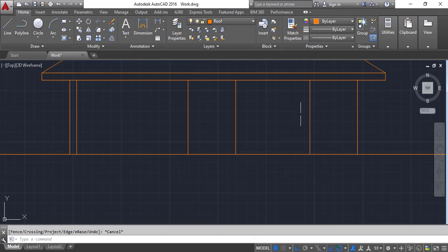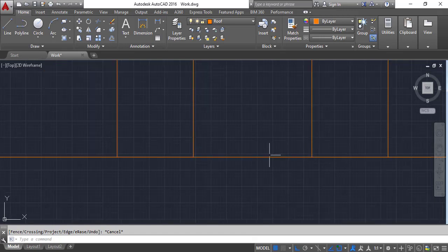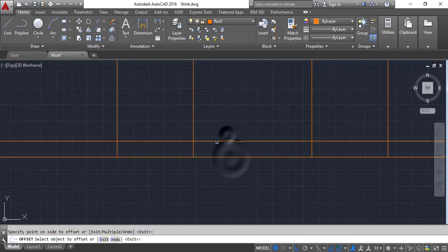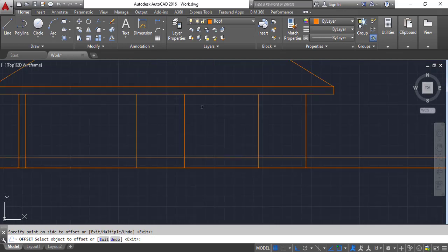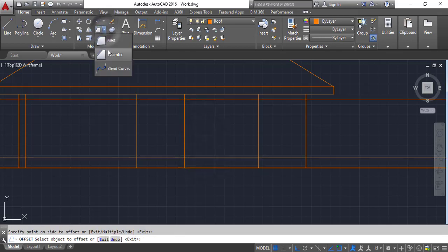And here this is my door, and this is my window. In here I'm going to keep my window height 1 feet. I'm going to leave this wall 12, enter, and here to here I'm going to keep a 6 feet offset, 6 feet, enter, and make it chamfer.